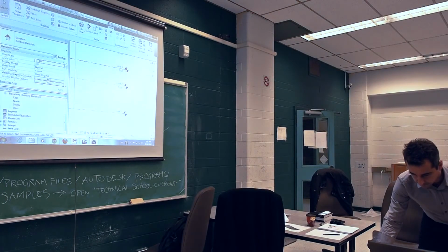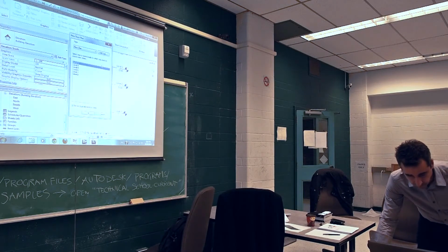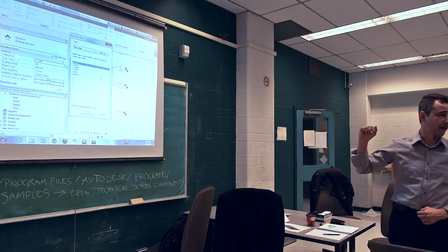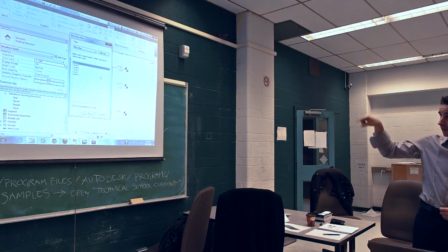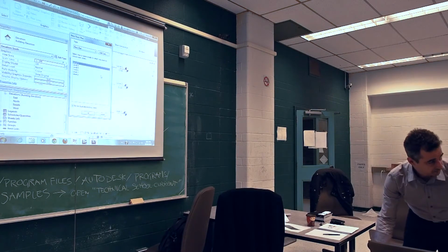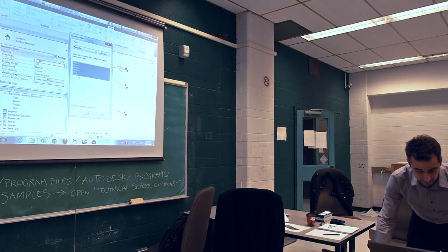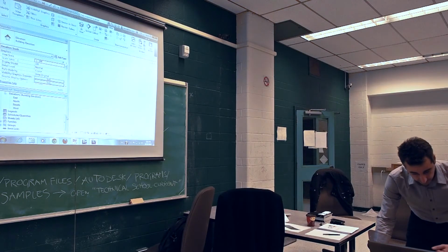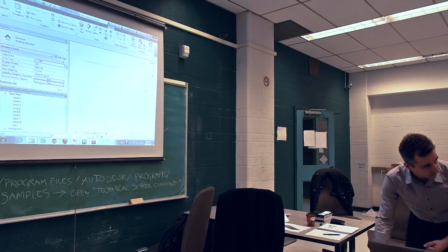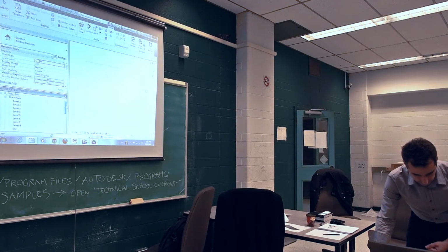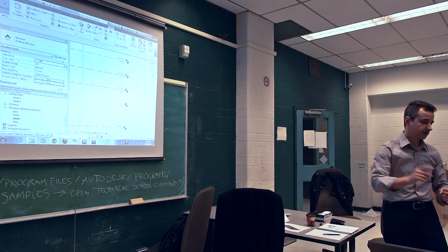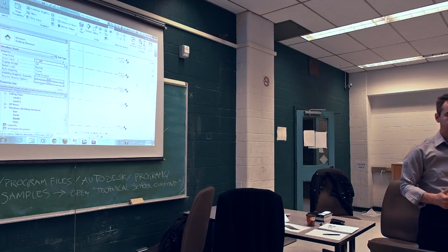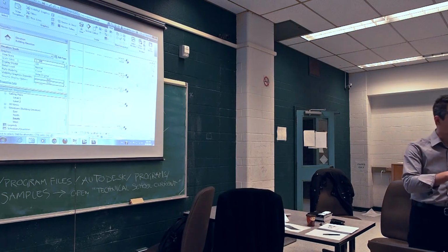How do you convert it to a blue one? If you go in the View menu, Floor Plans. So if I go to View Floor Plans, it knows that I created levels from 3 to 8 that don't have floor plans. So it's going to ask me, do you want to create a floor plan for these levels? And I can choose the ones that I want to create floor plans for, or select all of them and say, okay. If I do that, now I have all these floor plans that correspond to those levels. If I go back to my south, everything is blue now. Yeah? So that applies to sections, elevations, levels, callouts, pretty much everything that should lead to another view.